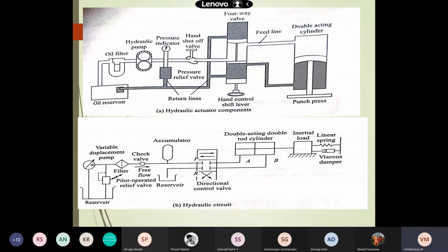There won't be any power source with the second idle gear. Oil comes in at the suction port, fills the space between the teeth, is carried around the periphery, and is finally pushed out to the discharge port. This is the working principle of the gear pump.